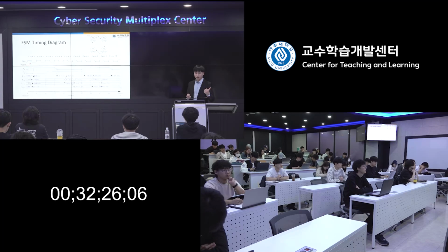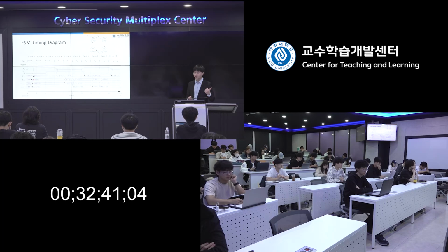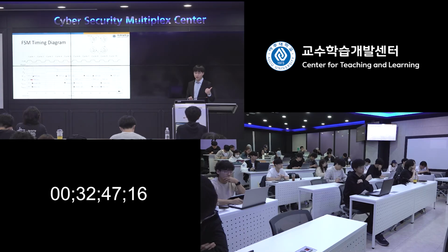If you look at here, you have a reset. You look at the state transition diagram. When you have a reset, you will force the state register to be 0, to go to S0. So it will immediately affect the state register. Once the state register receives this reset, it will cause the RA and RB.